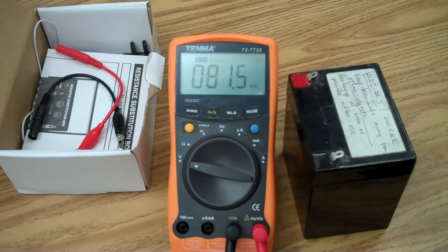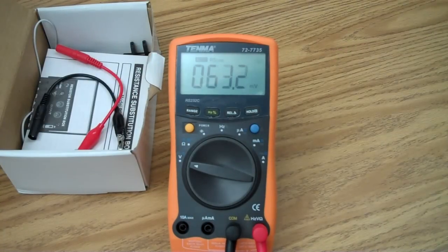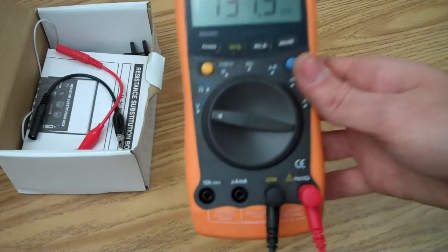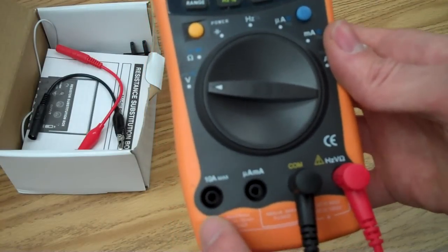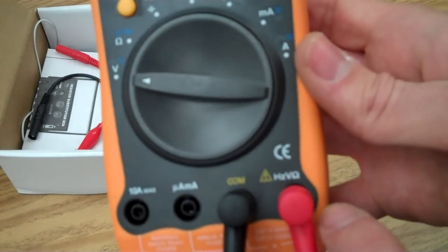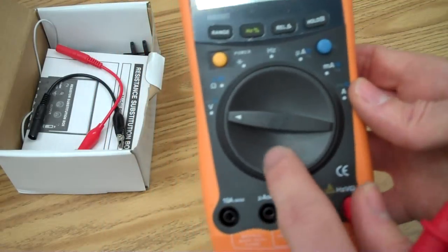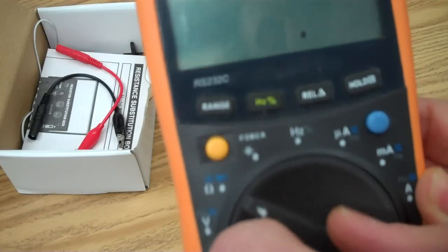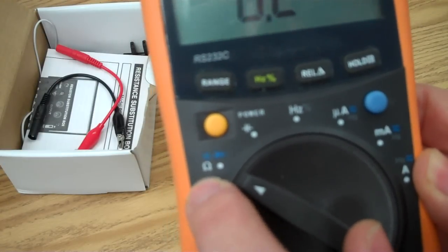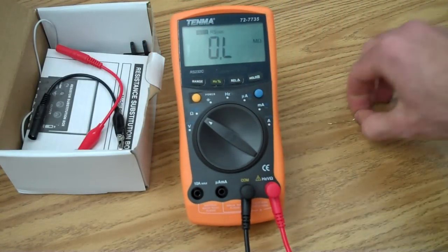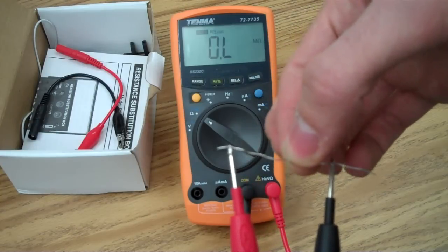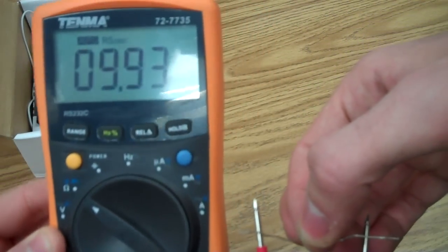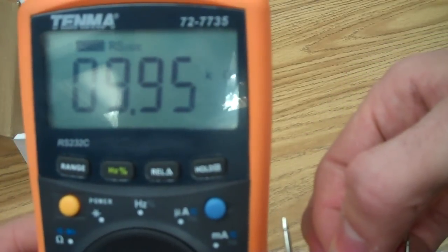Now, if we want to look at resistance, we have a resistor right here, and we have to rethink how to set the multimeter up. We look at what port we're plugged into, and we see here that we're in the resistance port, but we also have to check this dial. Before, we were plugged into the voltage; now we have to switch the dial to this ohm signal, which means resistance. To measure the resistance, we simply put the test leads at both ends of the resistor, and we see that it is a 10 kilo ohm resistor.